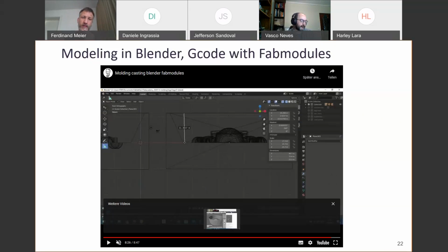And another thing that you should take into consideration is when you vacuum your silicone, it is going to grow. So if you can make this even higher, then you don't fill your mold completely with silicone, but you have some extra space for your silicone to expand.